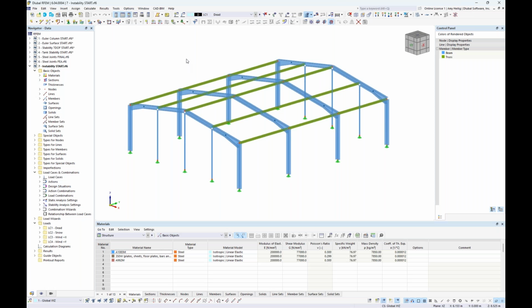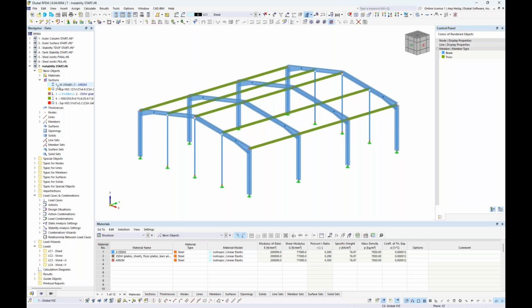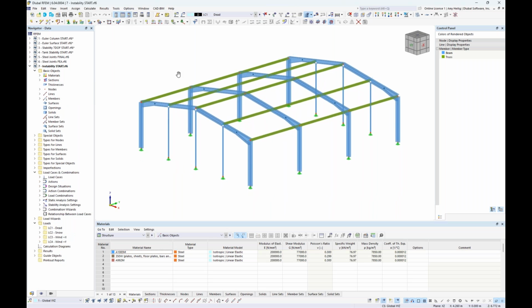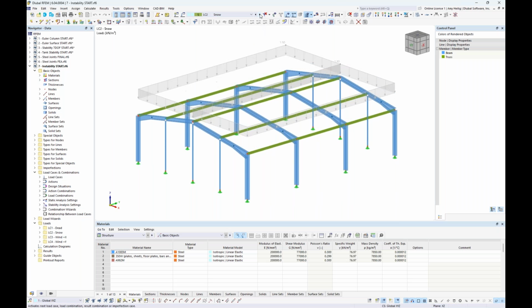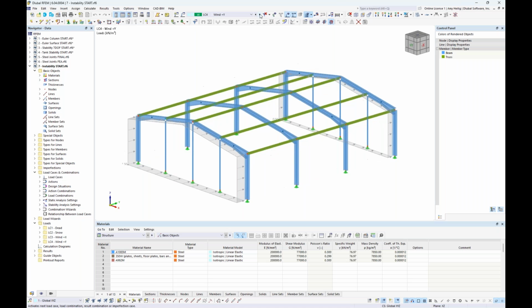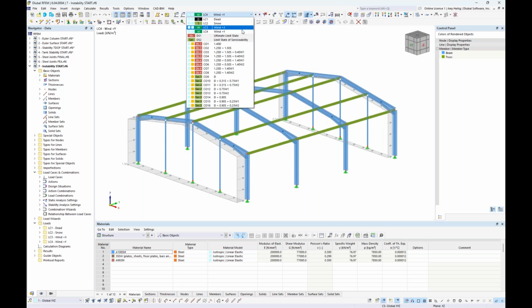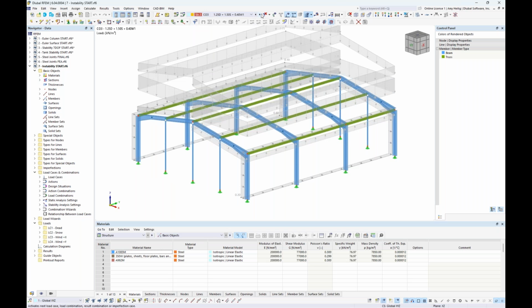So we have here just a general steel structure, again, modeled with all beam elements, and these come directly from the CSA standard this time with W250 by 80 steel shapes here, some HSS members, and so on. I also have some various applied loads. So we'll see the dead load applied here is an area load. We have snow load, and then we also have actually a couple wind loads in the global X direction and the global Y direction. And all of these are combined into load combinations here according to the NBC standard.